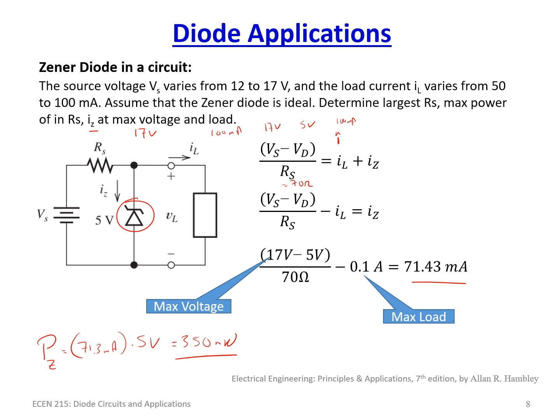This circuit is known as a voltage regulator, a very simple voltage regulator. There are actually other devices, but because of this, we're always going to maintain 5 volts right here on this terminal, which is great because if you have a load that needs 5 volts, for instance, a Raspberry Pi, and you had a varying input source, you can always maintain 5 volts. The only problem is this Zener diode is going to dissipate energy as heat. In this case, 350 milliwatts worth of heat.